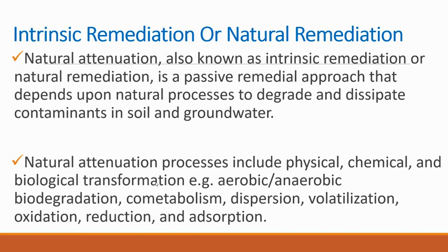In other words, in intrinsic remediation, you are allowing the indigenous organisms to actually do this work. Now, natural attenuation processes include physical, chemical, and biological transformation. Examples: aerobic and anaerobic bioremediation, co-metabolism, dispersion, volatilization, oxidation, reduction, and adsorption. This can happen naturally in natural attenuation.